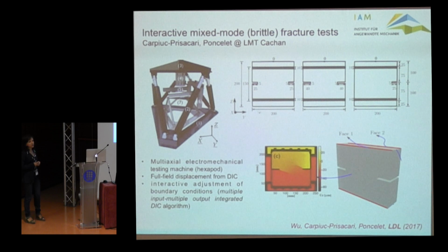And secondly, they had full field displacement measurements through DIC. So in other words, we had the possibility to know exactly the boundary conditions on the external surface of the specimen, at the top and bottom, where the specimen was loaded. At the same time, we could then also compare our computations with the surface fields that were also known on the side surfaces.